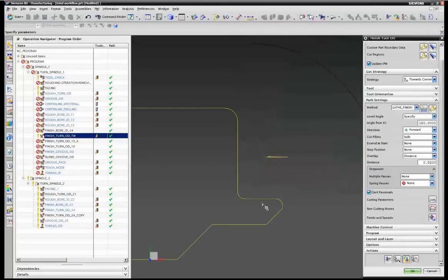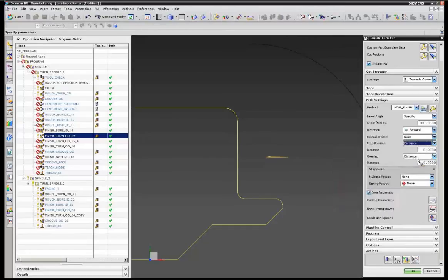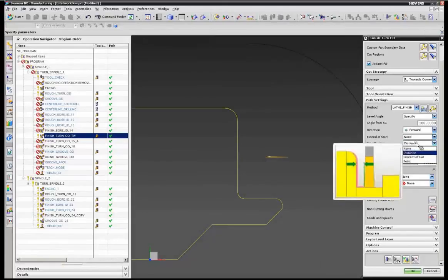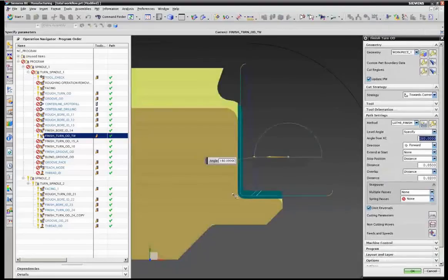The option to define where the change will be is also overruled by the definition of the stop position. In that case, you're able to work outside of the corner. In that case, you have the choice between using a distance, which moves from the split point in the middle of the corner to the first cut.